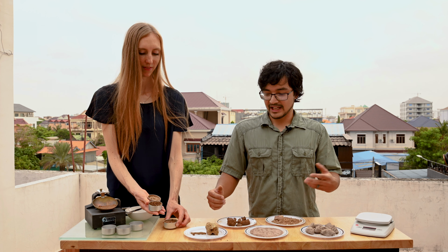One thing that you'll also observe in some soils is cementation. In some soils, they behave more like a rock, and you actually have to use quite a bit of force to break the particles apart. So cementation ranges from lightly cemented, where it's pretty easy to crush with your hand, to well cemented or highly cemented, where it's harder to actually crush the soil. So this one is a little bit harder, and I'm applying quite a bit of force and it's not crushing. So we would call that a highly cemented soil.